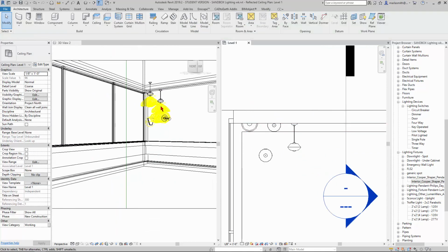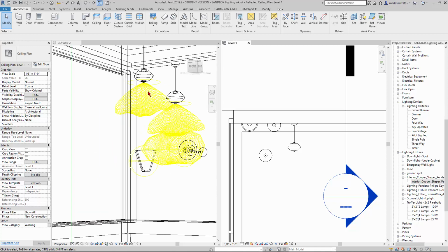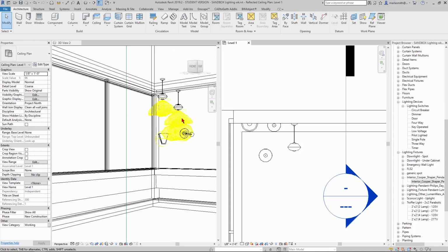You'll notice you can see the lighting fixtures in here, the actual beams. This is an IES file, and this is just a general lighting file from Revit. These IES files actually come from the manufacturer and render out the actual beam of the lamp itself that they've analyzed. I have those turned on in this view, so I'll show you that, and then we'll go and take a look at downloading and how that works.